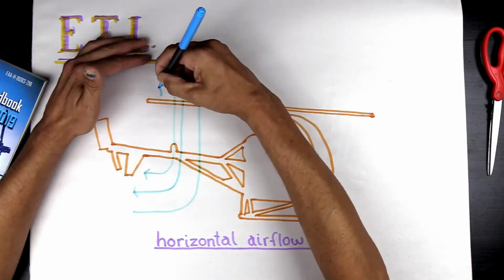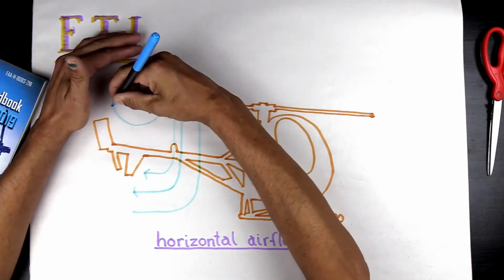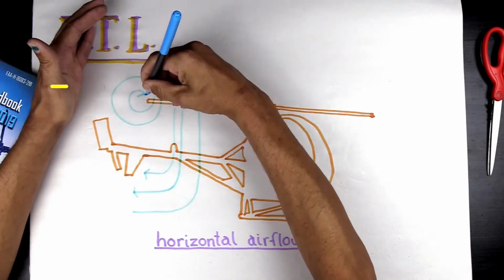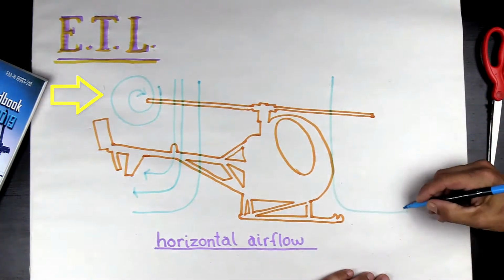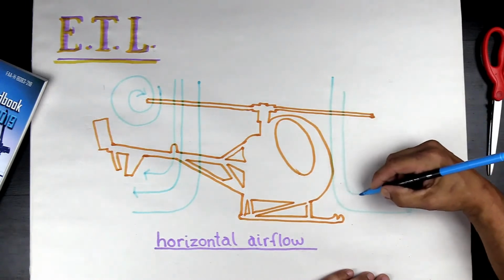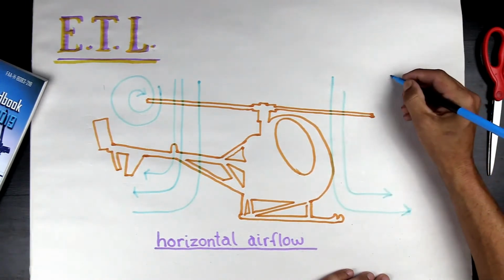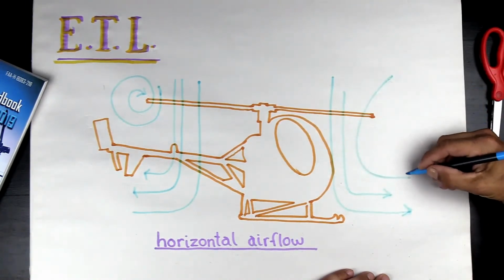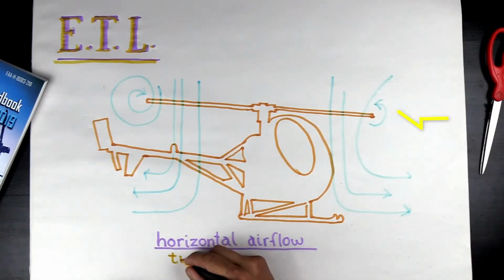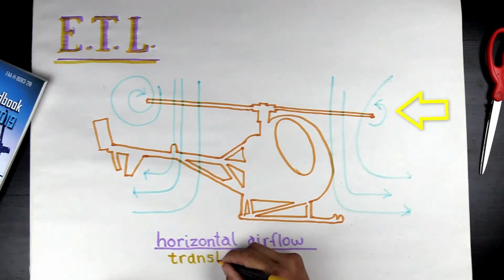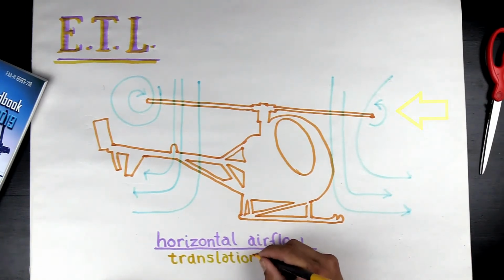In the back half of the helicopter, really nothing has changed. Still coming down, going out. Vortice. Front half, mostly the same. Probably right here is the same, but then the air isn't quite coming straight down. Now it's starting to shift and come in a little bit more like this. And your vortice is being reduced a little bit and being blown away just a little bit.